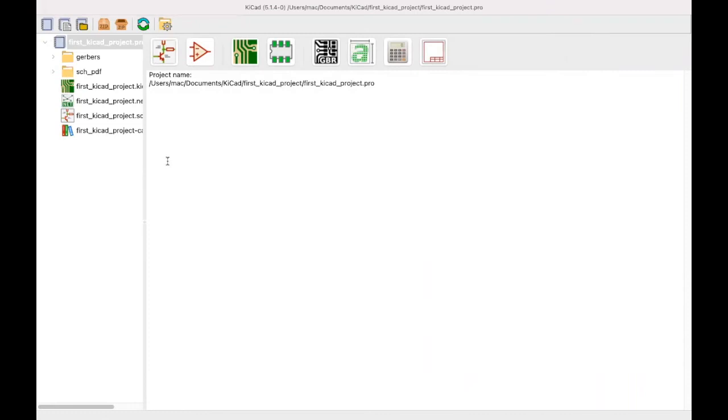Say maybe you are designing, you thought, well, 2 layers might work for this board, but then moving forward, you realize that all my traces cannot fit. So several factors might lead you to a 4-layer board or 6-layer board. One is if you have so many signals and they cannot fit on top and bottom. So maybe this is a good chance for you to take some notes. It's when we have a lot of signals and they cannot fit on top and bottom, say when we have so many components and they take a lot of space.